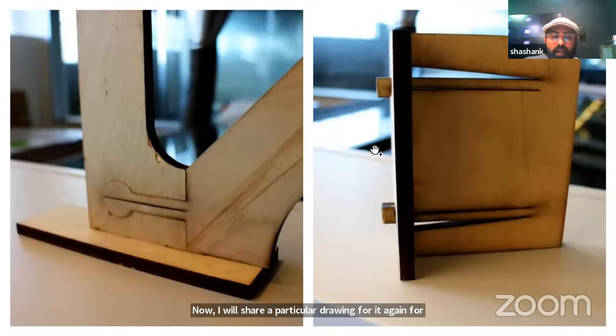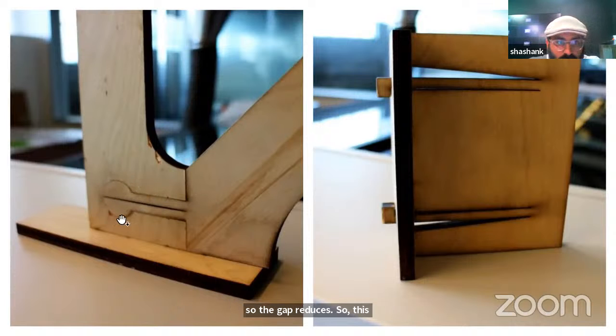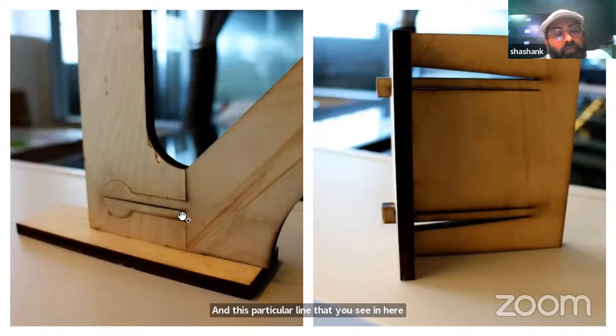Now, this is a clipping mechanism where these two pieces are basically straight, but once inserted, there's a gap here. The gap reduces. So this particular hole which you see here is a reduced hole, and this particular line is much wider. So you're pressing it and then inserting the entire detail. Once you press it and put it inside, inherently this will have a spring action on top and bottom. One part will go up and the other part will go down, and automatically it will lock itself.